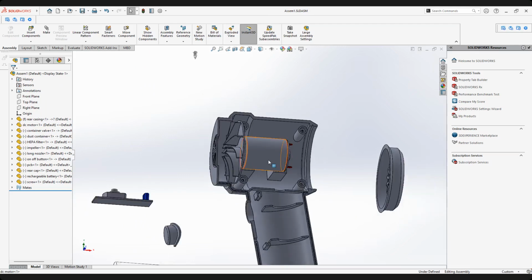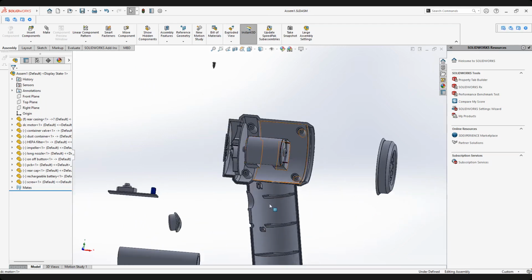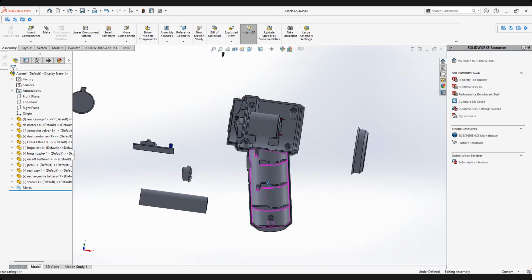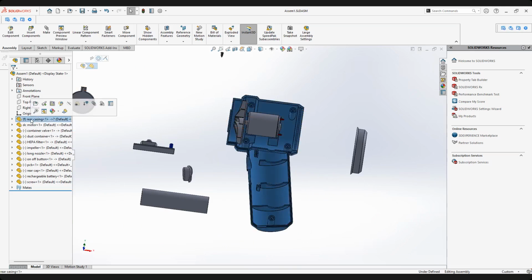Okay, now, motor number 2, impeller number 3, what is number 4? Motor number 2. Okay, look on the screen. First, part number 1 is right. The order of the list in your feature manager will be your part number when you do balloons in the assembly exploded view.